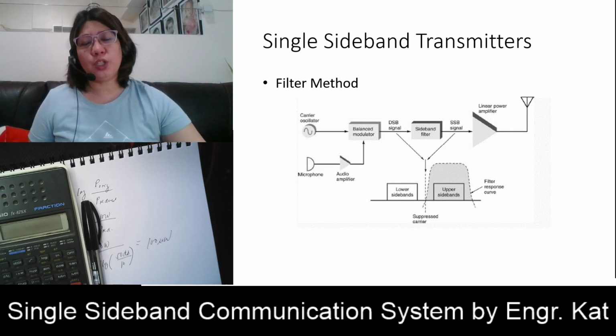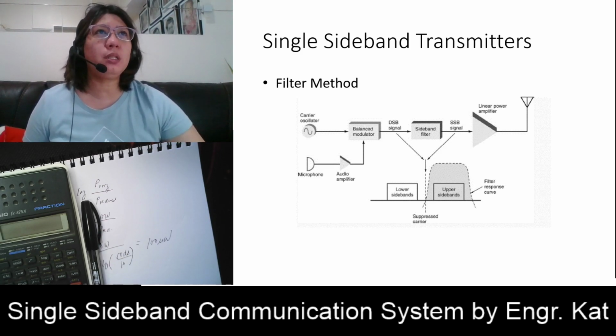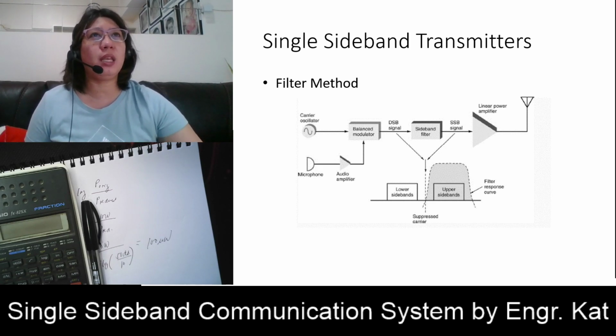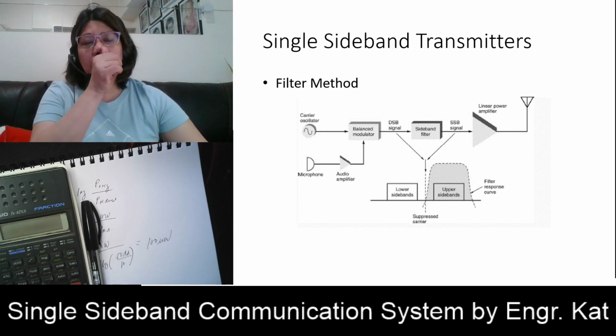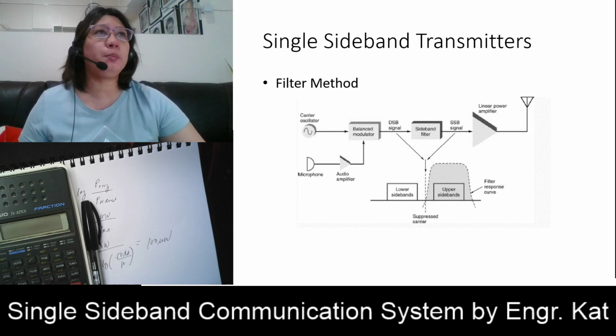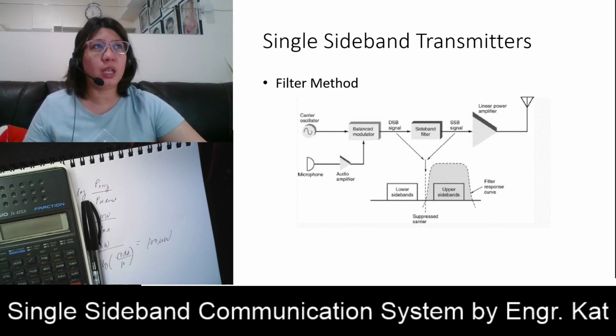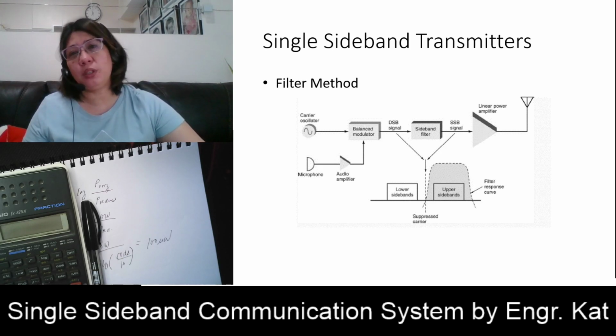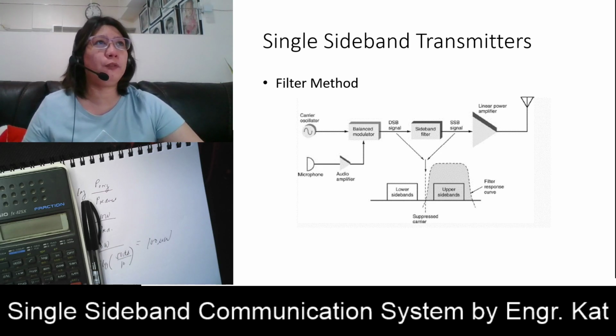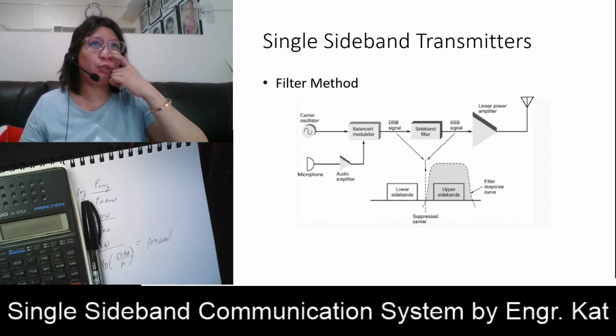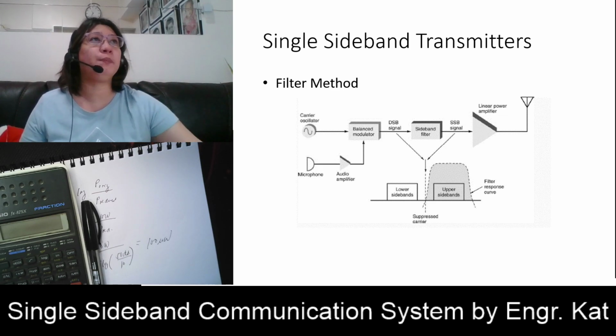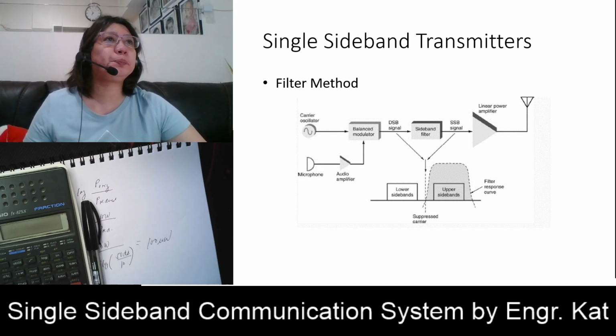The transmitters used for single sideband suppressed carrier and single sideband reduced carrier transmission are identical, except that the reinserted carrier transmitter has an additional circuit which adds a low amplitude carrier to a single sideband waveform after suppressed carrier modulation has been performed.